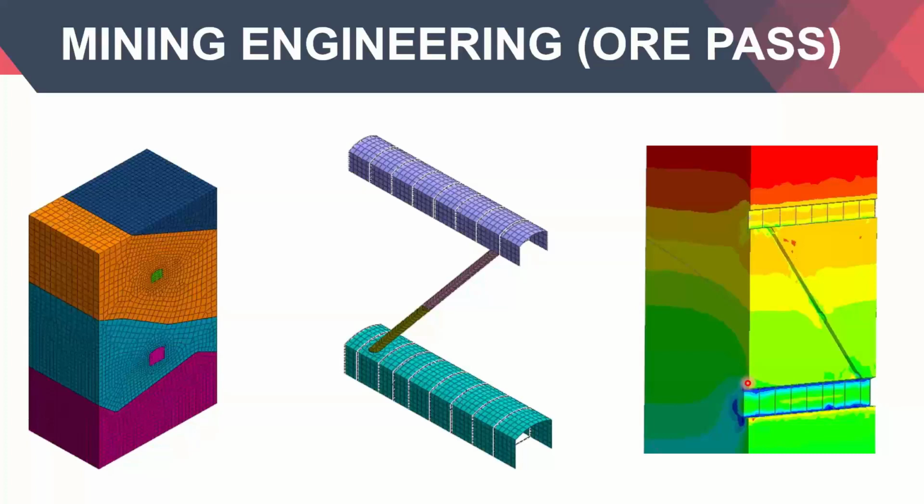But since it is an FE model and the model converged, that means as of now the wall is safe. For how long the wall is safe, we need to do a creep analysis, a parametric analysis, or a probability analysis.